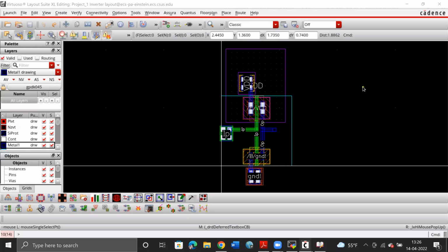For the next part, let us make a silly tiny change in the layout that we have already built. I'm going to draw the output metal wire to an extremely huge length and see the effects on the working of the inverter. So why are we doing this in the first place? As we discussed in the previous video, wires contain parasitic resistances and capacitances that slow down the transfer of input to the output. So it's nothing but an exaggerated implementation of parasitics from the inverter.